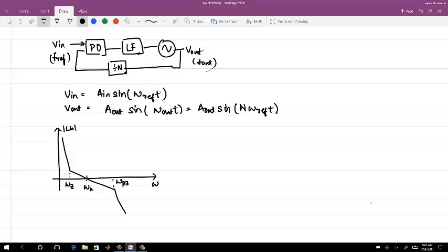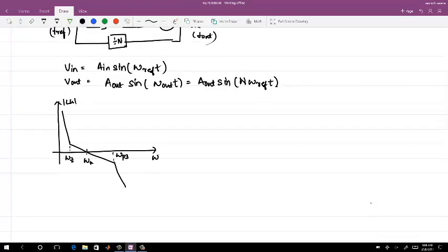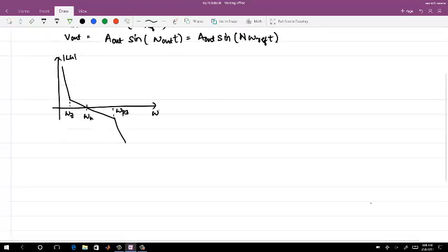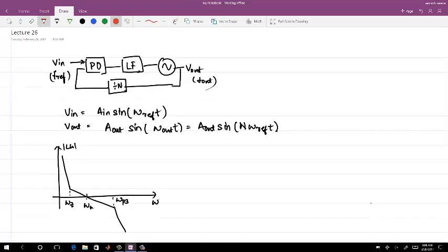All this frequency analysis which we showed was with respect to DC, meaning the loop filter response, when we use any RC, is with respect to the DC frequency. Now the question is this: I am injecting something at the reference. We have seen the reference spurs. So let's say I injected some voltage or some pulse at every reference. Tref is the time period.